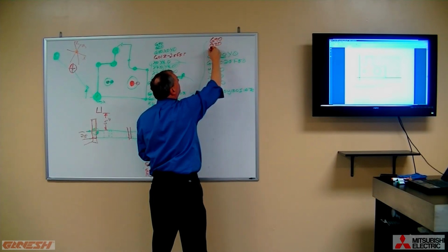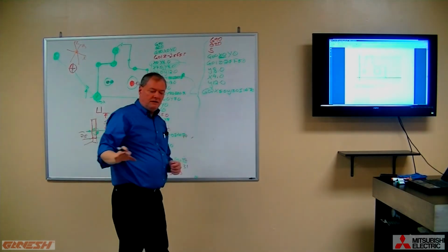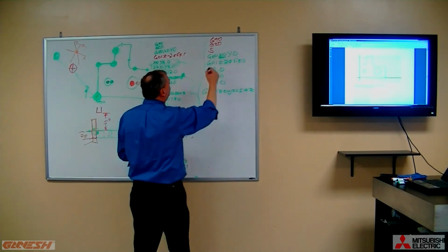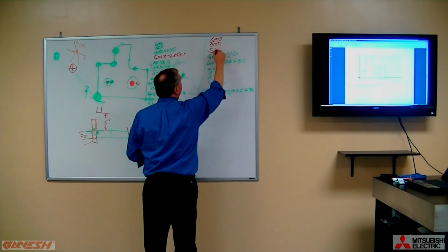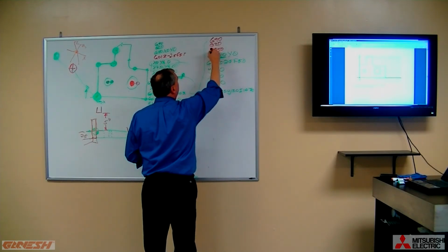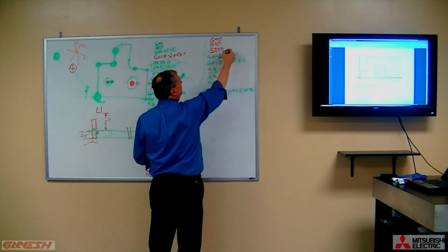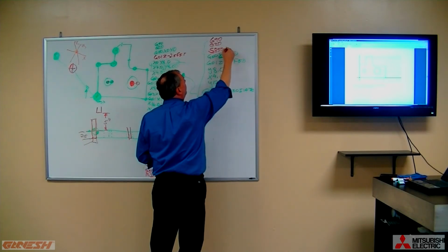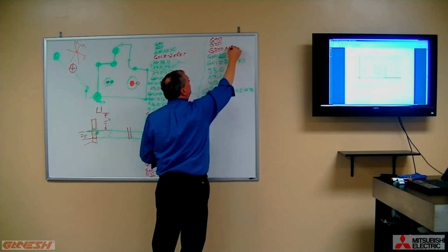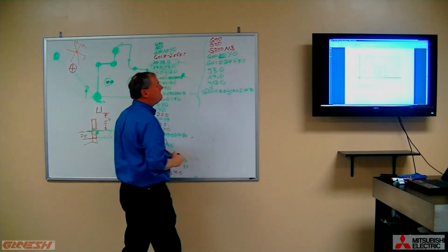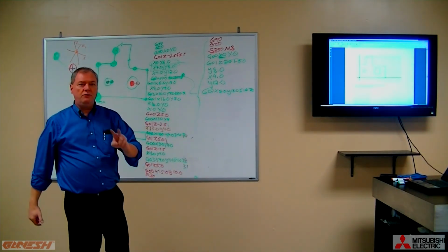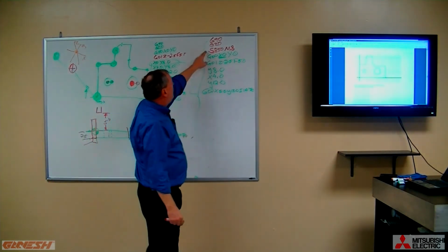We will insert the letter S for spindle. Now some RPM value. So if we want 850 RPM, we say S850, and then the letter M, and then the number 3.